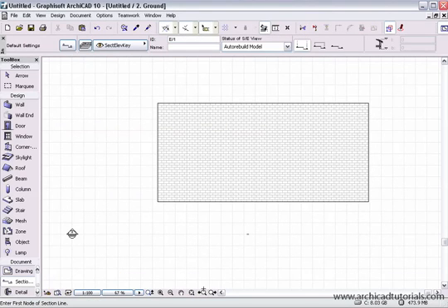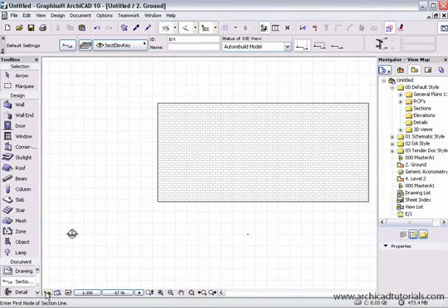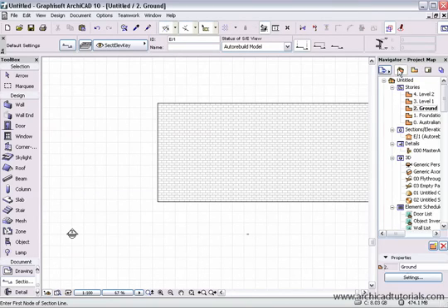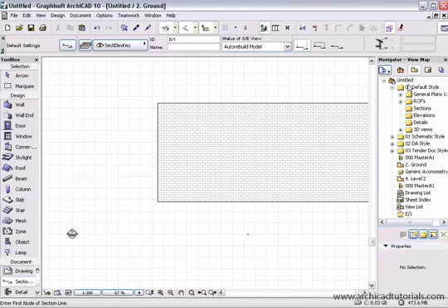In addition to the tools we have available to zoom around our model, we also have the navigator, which is basically a tool to help us navigate around our file of our model. So first of all, the project map gives us our raw views of the model. Our view map gives us specific views of the model with the intention of creating a specific type of drawing. So they'll have a certain style, layer combinations, and things will be turned on and off so they will look